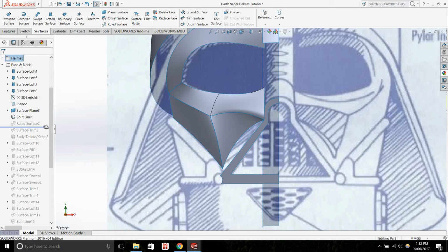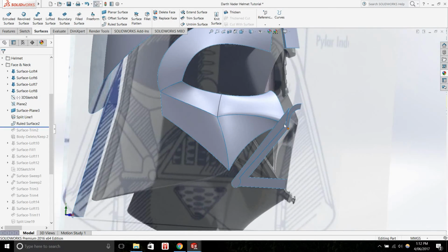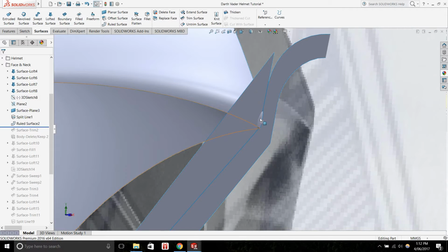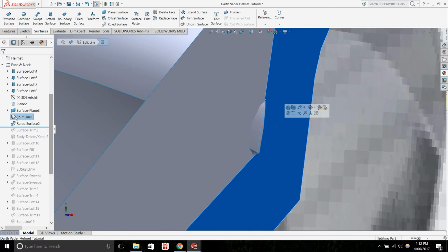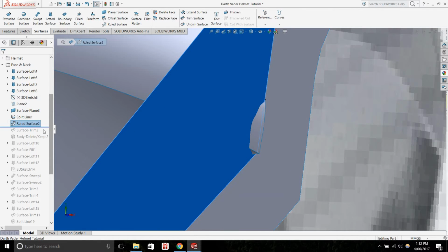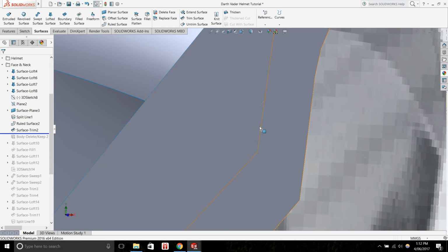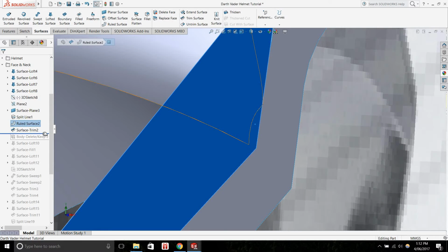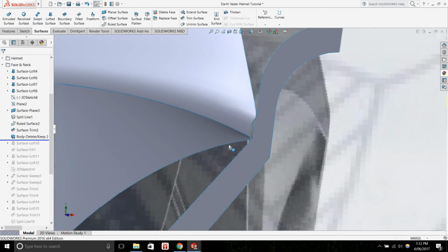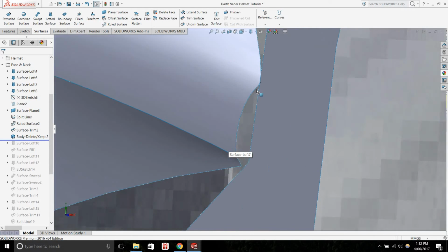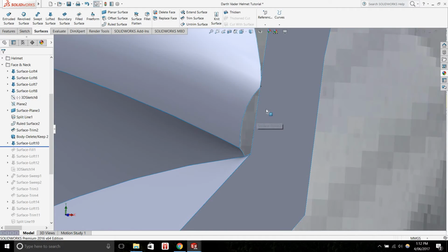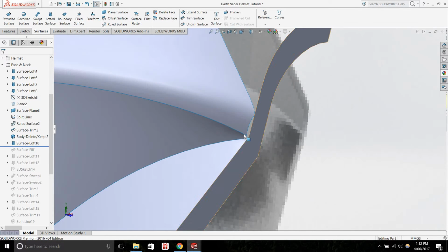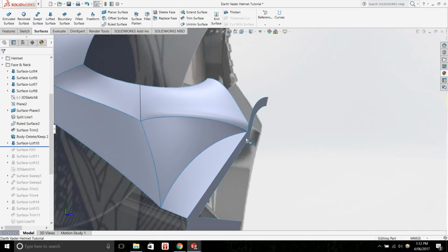And just quickly going through it. This is probably just me being inefficient. These surfaces didn't match up just here, so I had to create another ruled surface and then trim that surface back and delete that ruled surface that I'd created. Essentially, those steps were just to get these to end on the same plane so that I could stitch them together a bit later. There definitely would be a more efficient way to do that, but yeah, this model isn't perfect.